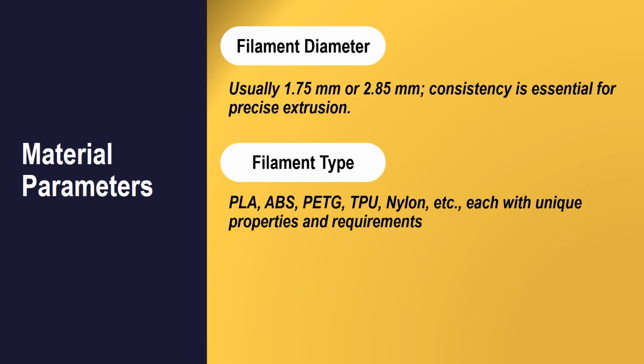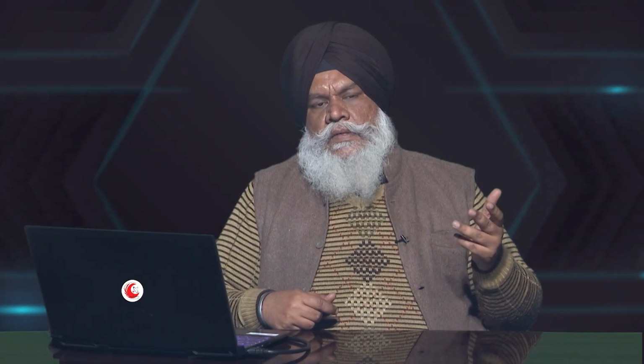They have unique properties. If you are interested in a biocompatible part, PLA based filaments are used. If you are interested in high strength parts, like car bumpers or the dashboard, we are interested in ABS.